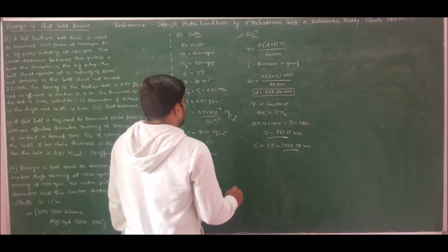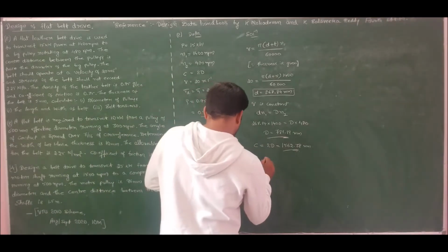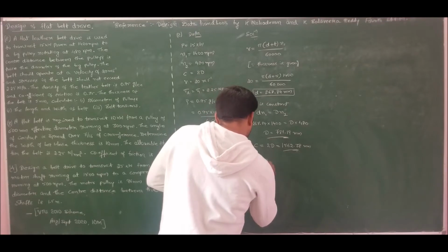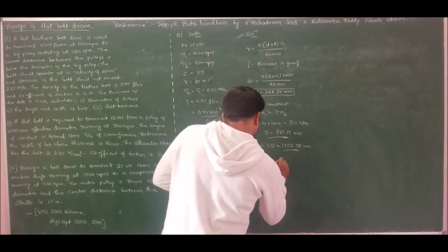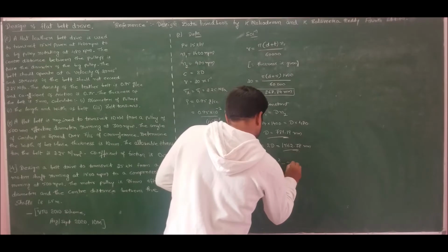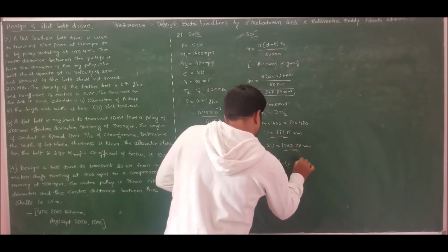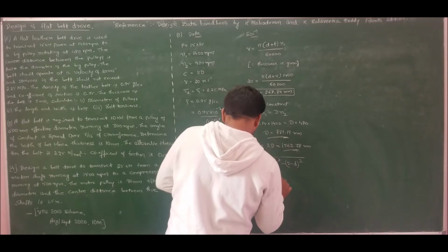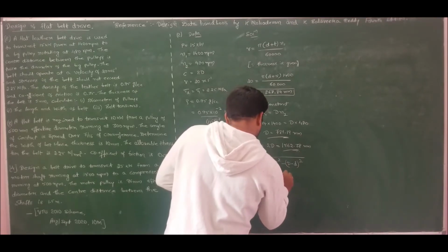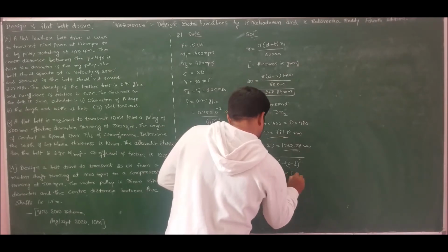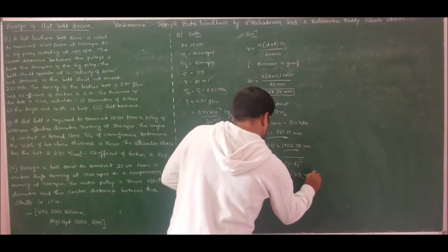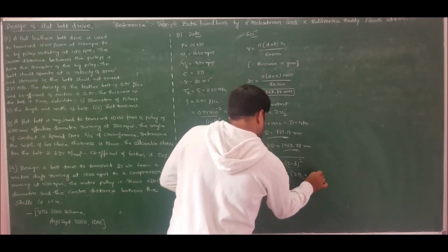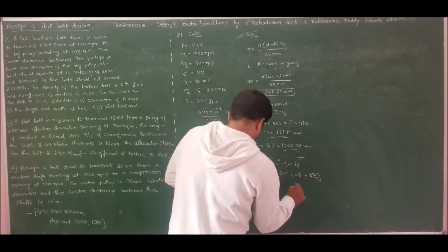Next, moving to calculate the length. Length of belt is given by L is equal to the square root of 4c square minus d whole square, plus half of D theta L plus d times theta S. This is equation 14.2b.